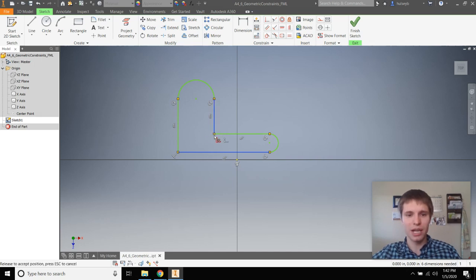It shows up as either a line or those icons for coincident. In order to grab the point, you have to make sure that it's highlighted with a little white circle. Okay, so I can move a bunch of stuff around, but when I'm constraining or moving other things around, I want to make sure that one thing is locked in. So that's what fix is for. I can fix different parts of my shape. If I like where they're at, or if I like how big they are, I can just fix them right there.